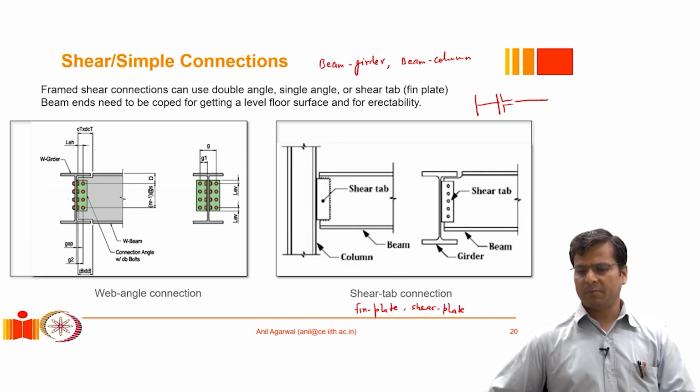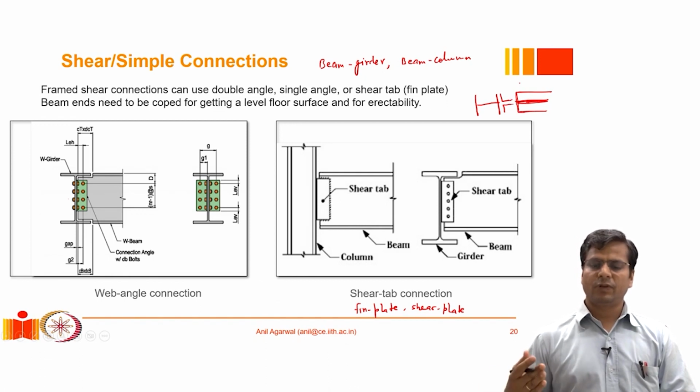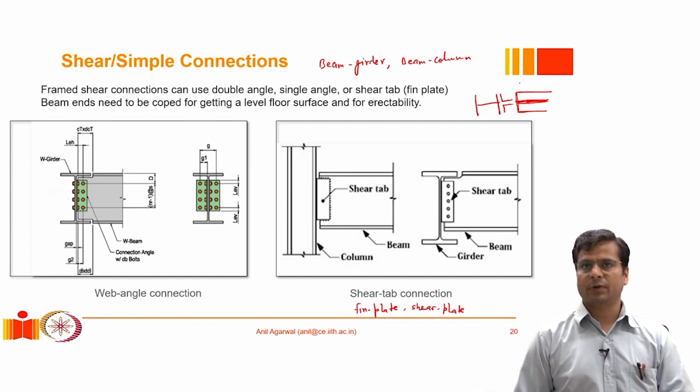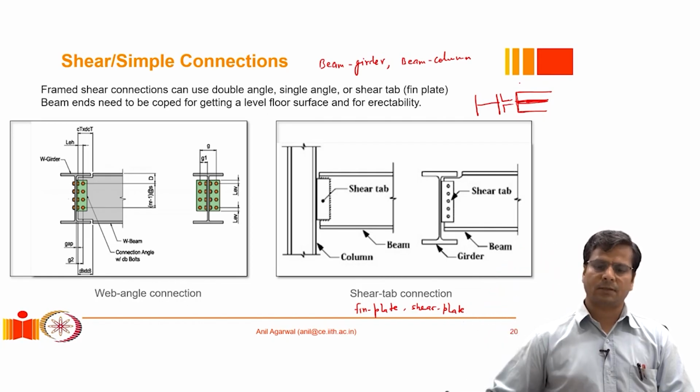So the web of the beam can barely fit this gap, right? That is the idea. And so this is the web and this is the flange of the beam, the flange width of the beam. And this needs to fit inside. But at the site, we don't have space to pull the beam back and then slide it in. That's very difficult. Usually we have to lower the beam at the site, which makes it very difficult to place, right?